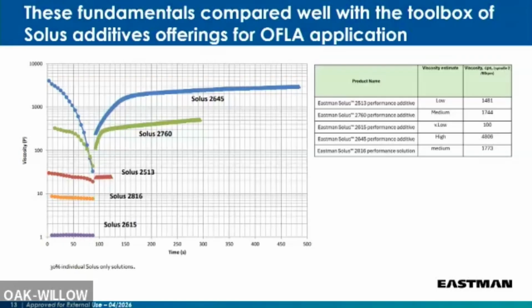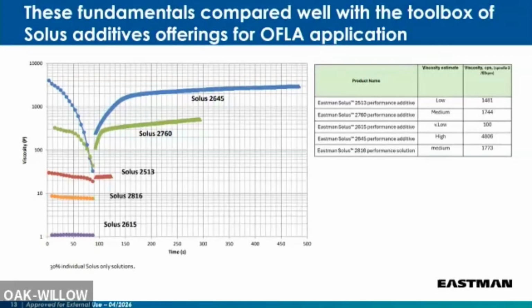When you go to the suppliers, they have their own formulations. Their part A is totally different. Some of them may have very good sag properties. They may not need this aggressive rheology modifier. They may need just this or this over here. Some may have a very weak part A. The SCA part may be very weak. They need very aggressive recovery. They may go for these samples.